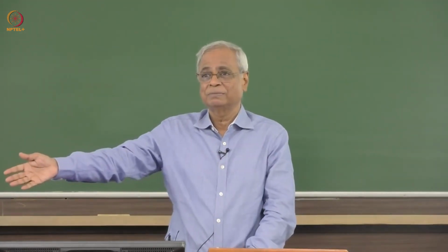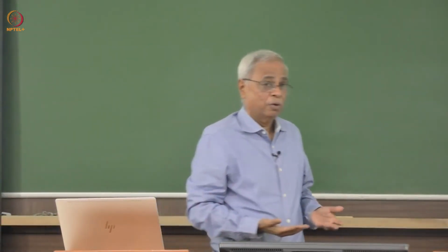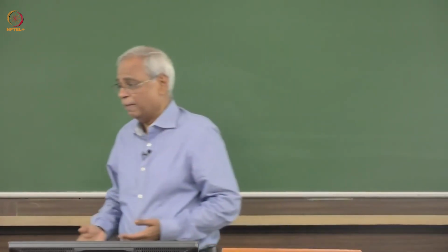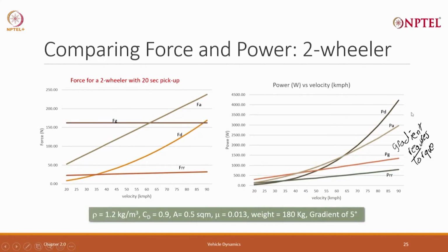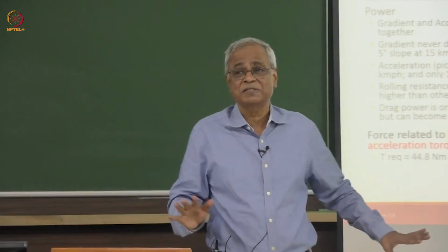That is what is required, and it comes straight out of this simple work. The battery requirement will also go up, because you will consume a lot of energy. Remember, power is high, and when power is high, energy consumed also will be high. So, you will require a larger battery, and cost will go up. So, the vehicle starts at 1,20,000 rupees in India. Do you understand why there are two distinct kinds of two wheelers? Your battery changes, your motor, controller, everything changes.